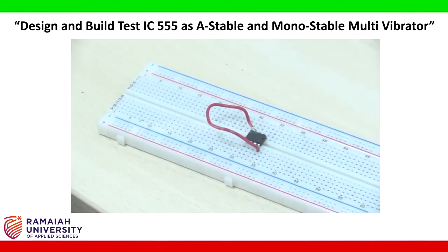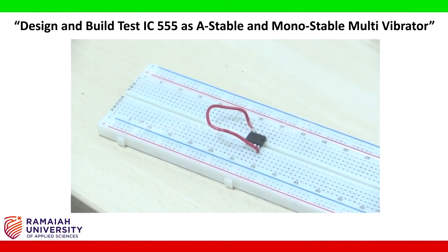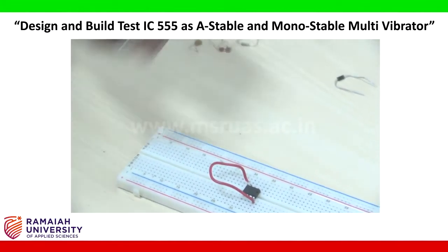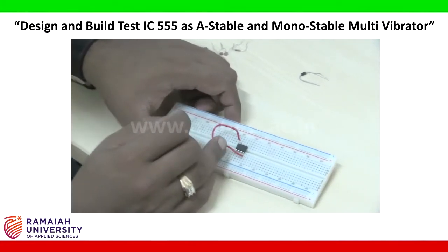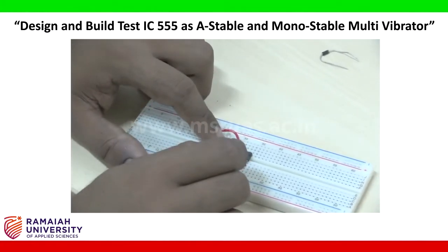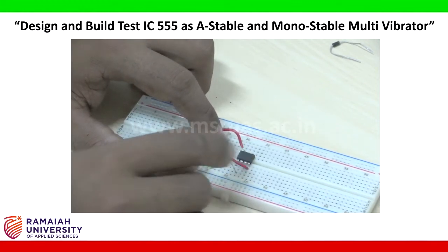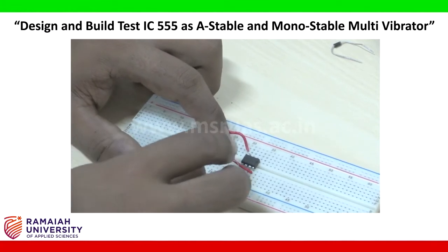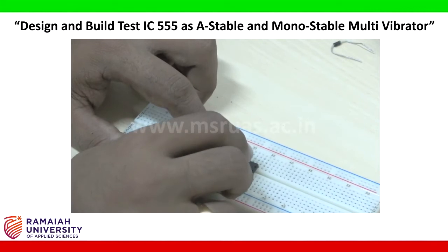Next I am going to connect this shorted pin with pin number 6 through a 10 kilo ohm resistor. So I am taking one 10 kilo ohm resistor, and I need to connect it to either 4 or 8. This is pin number 5, 6. This is pin number 6. This pin number 6 will be connected with the 10 kilo ohm resistor to the shorted pin 4. This is 4.